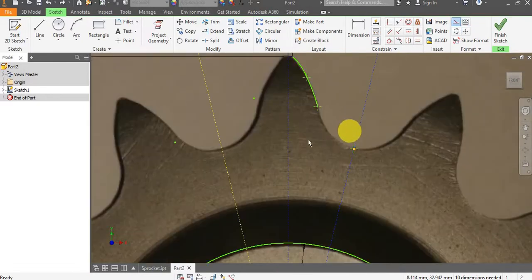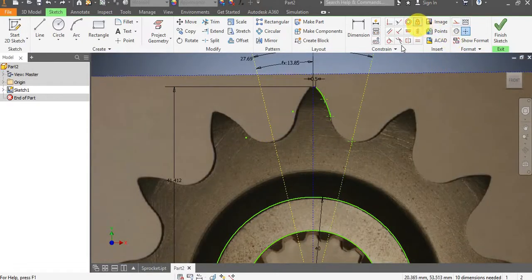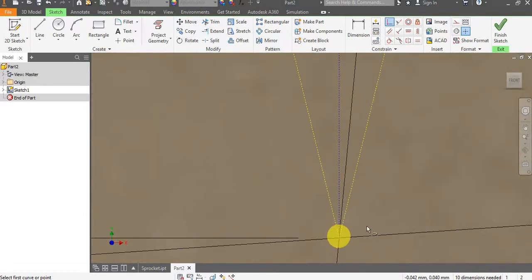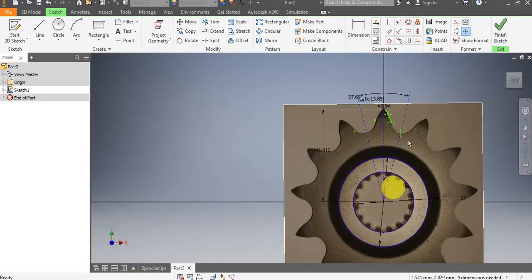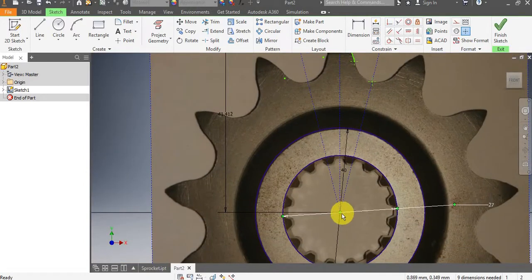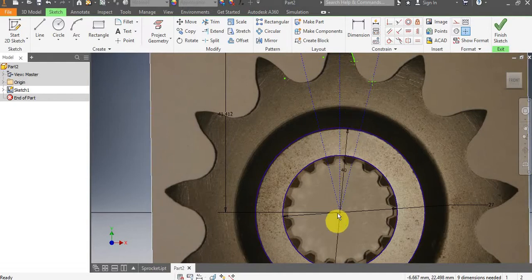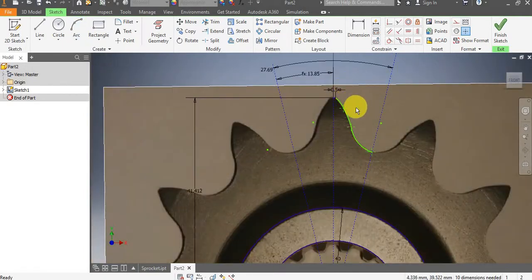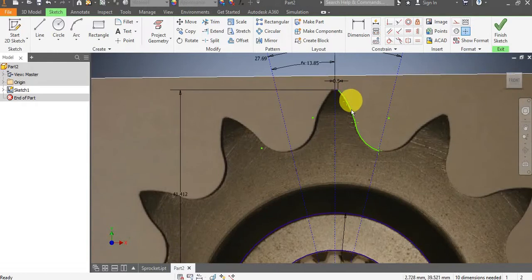Just notice that these 2 lines were moving, so I'm going to fix them first. So yeah, I thought that all these lines need is a coincident constraint. So now that they are constrained there, we can add our final arc that goes from here to here. So we've got our geometry now from these 3 points.